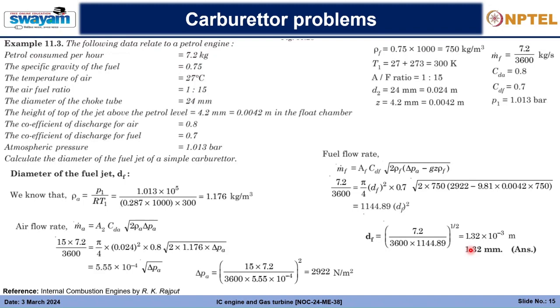Instead, we need some auxiliaries, the power system or the idling system. We have learned in this session that a higher fuel-air ratio, a richer mixture, is required, which cannot be supplied by the simple carburetor. We need an idle system.